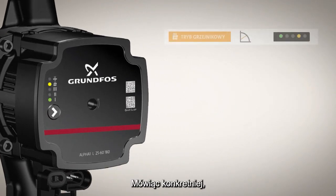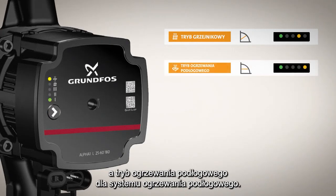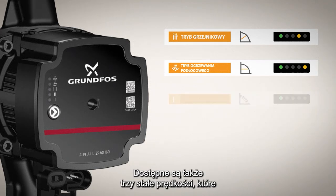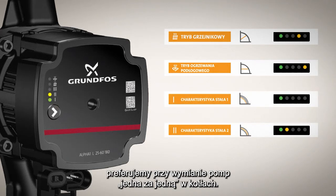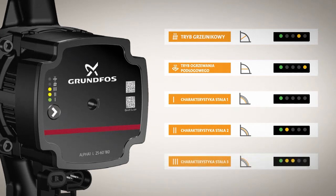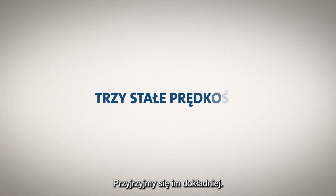To be more specific, radiator mode is for radiator systems and underfloor heating mode is for underfloor heating systems. And then there are 3 fixed speeds, which are intended for one-to-one replacements in boilers. Let's take a closer look at the 3 fixed speeds.